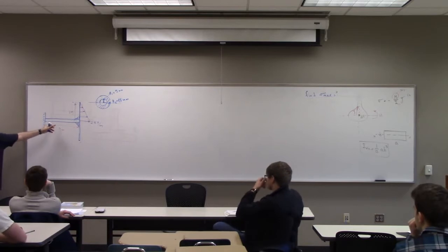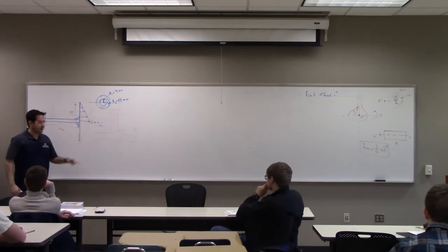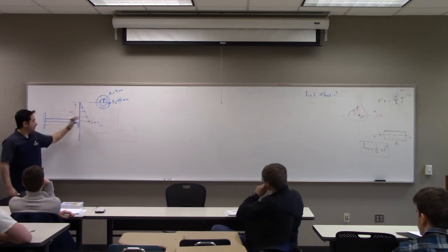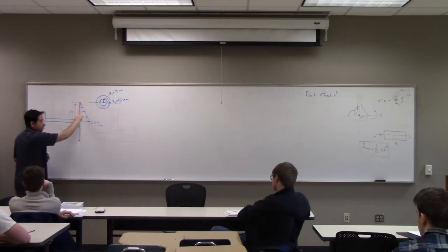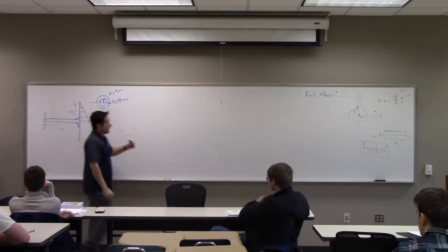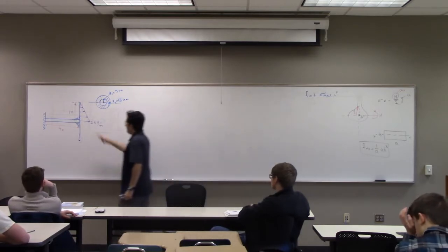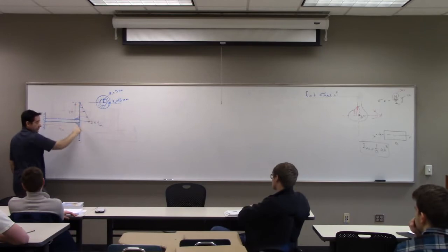If I take this as a system, how many unknowns do I have? 3. 1, 2, 3. Everything here is known. And this is massless and rigid, so it's only here to apply this load uniformly. This is one way. The other way is you can say, I can replace, but I'm not going to cut this rigid. This is not what I'm interested in. I'm not going to find maximum sigma in the rigid plate. So, in fact, this is not important, so I can consider it as an external load on that.